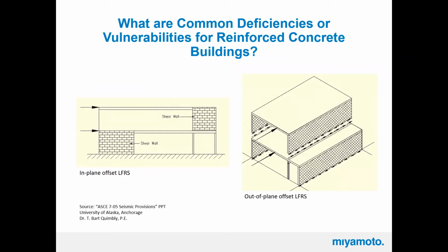Now we design all these things at what we call a mega level load, which is really the full earthquake response level load. Whereas for the rest of our building, we design on reduced loads, presuming or knowing that there's a certain amount of ductility. Well, with these sort of elements, we take out some of the reliance on ductility, so that they will behave well.